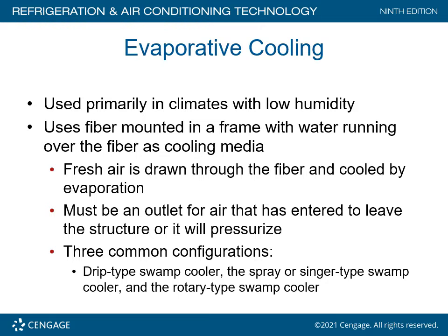If it's a rotary swamp cooler, it's going to be a large wheel that has copper or brass screen pockets to allow airflow through the screen, and there'll be a tank in the shape of a half moon, which is full of water.